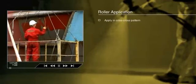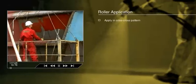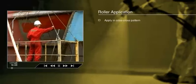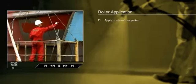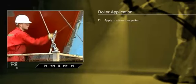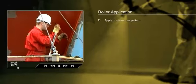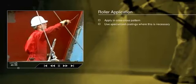In use, the roller is rolled over the surface in criss-cross strokes, working the material out evenly. Often, material is applied in this way and left, but if necessary, it may be laid off by passing the roller vertically or horizontally over the surface. As with brush application, many modern, high-build coatings are not suited to this method of application, and the application of a consistent coating film is not easily achieved. However, with specialized, high-build coatings, this is possible.